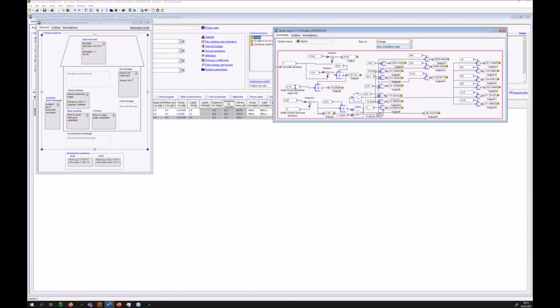The last thing is the solar pump mass flow, which also can vary with the optimal solution here, together with the solar collector size. So this is the area-specific solar pump mass flow, and you see here the parametric graphical scripting, for instance. So the width of south windows, from there just calculate the width of collectors multiplied by the height. You will get the area of the collectors, and this is multiplied by this area-specific mass flow to get the absolute mass flows, of course.